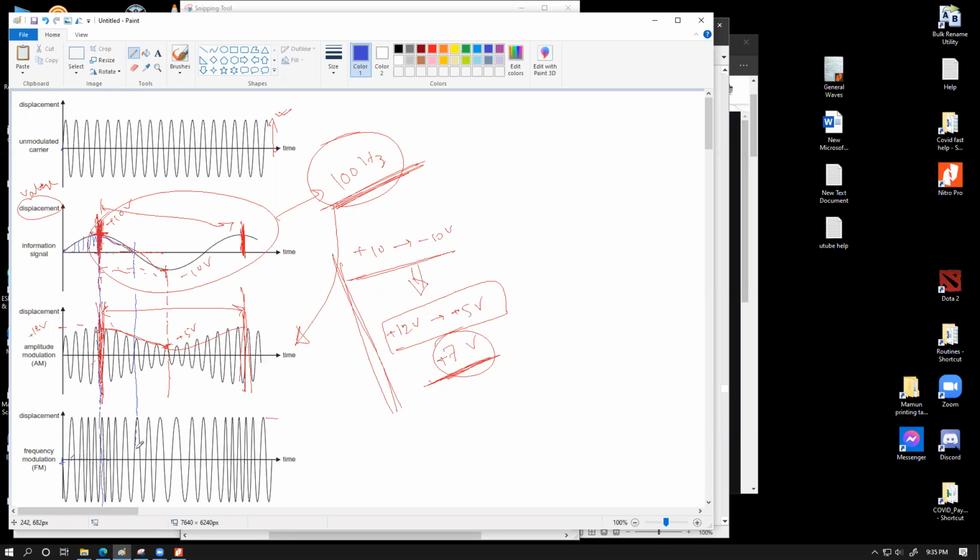the frequency of the modulated carrier would be exactly same as this one. So if this original carrier has a frequency of, let's say, 1000 hertz, I'm using 1000 hertz because I assume this one to be 100 hertz. This is supposed to be significantly larger compared to this one because it has to carry a lot of energy. That's why I'm choosing this to be 1000 hertz. So over here, at this location, this will be 1000 hertz. At this location also, this will be 1000 hertz because the signal is zero. This would be something higher. Now, how much higher? That also is defined by some scale.